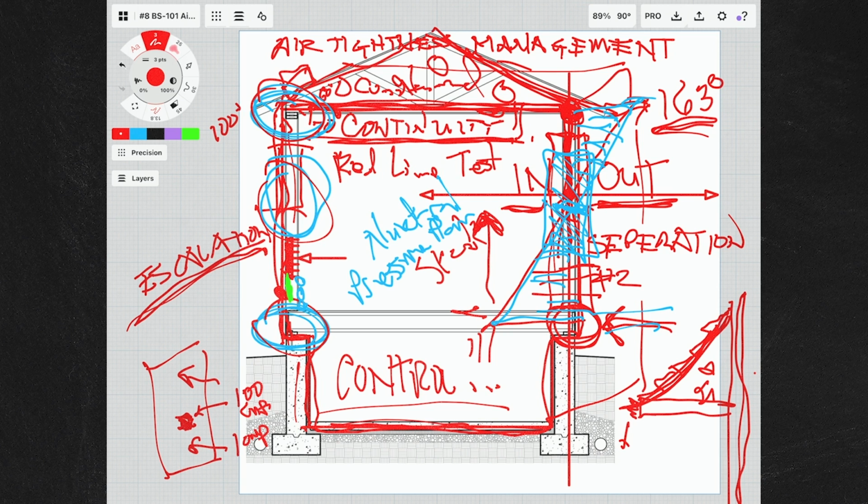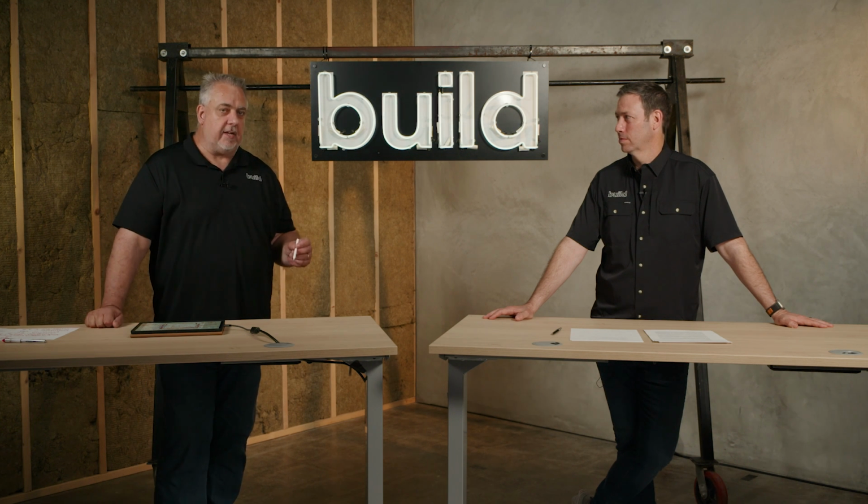So the exterior wall is leaking air. That leaky, moist air getting into this cavity. Guess how nice and warm the backside of that plywood is in the winter in New England? Cold. It's cold. So that water's condensing. But it's not only condensing, it's condensing on the backside of the plywood.